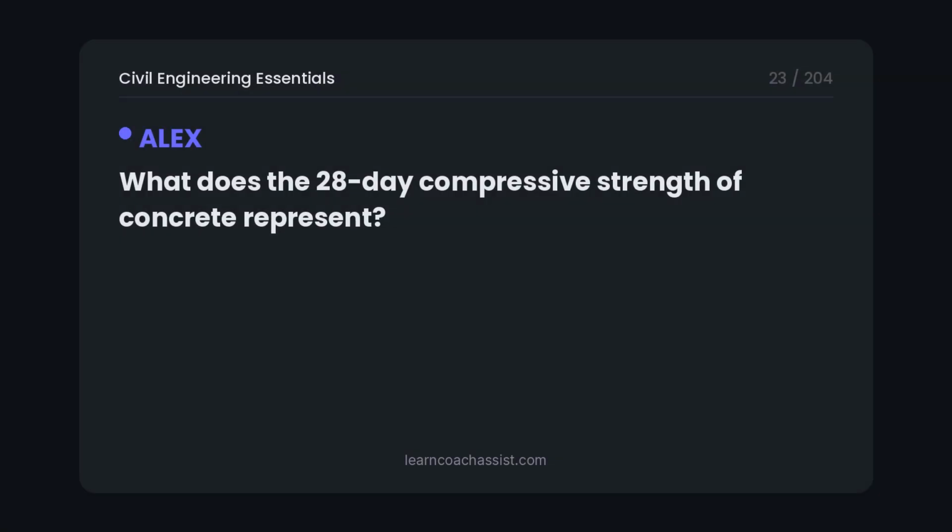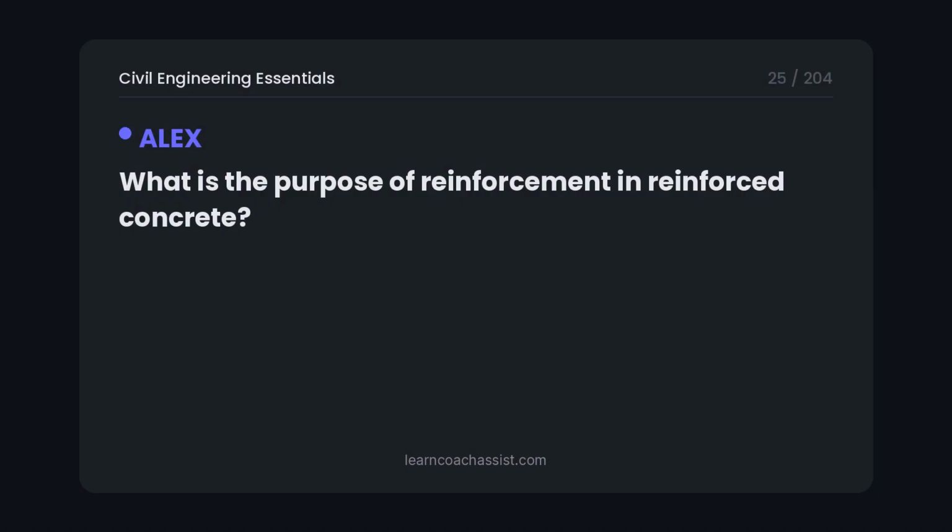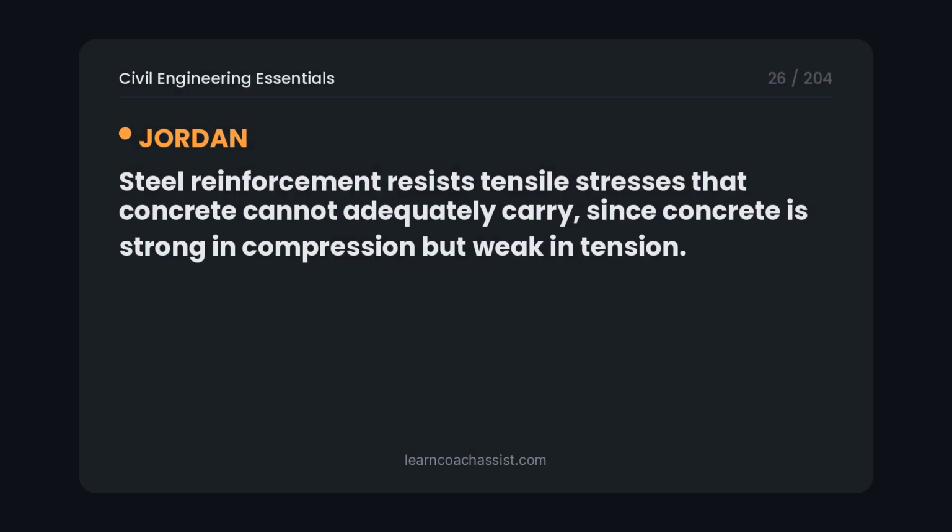What does the 28-day compressive strength of concrete represent? It is the standard design strength, f'c, measured by crushing a cylinder or cube after curing for 28 days under controlled conditions. What is the purpose of reinforcement in reinforced concrete? Steel reinforcement resists tensile stresses that concrete cannot adequately carry, since concrete is strong in compression but weak in tension.